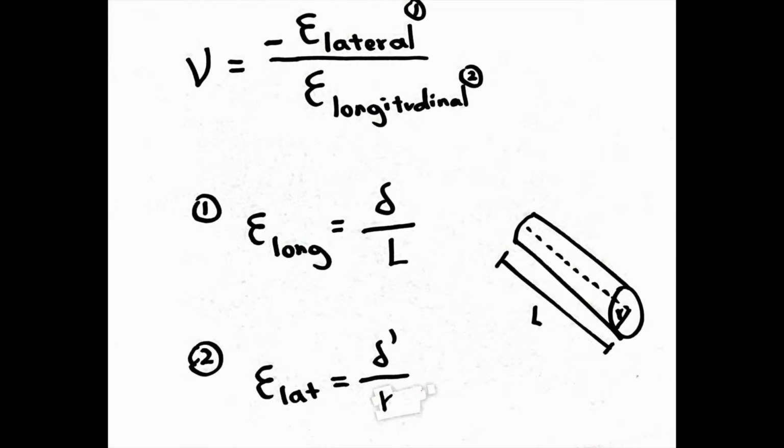So how do we determine the changes in material with Poisson's ratio? Poisson's ratio is defined as negative lateral strain over positive longitudinal strain, and each part can be further broken down with the strain deflection formula into strain equals deflection over length or deflection over radius, depending on the axis of interest, shown on this slide. Now let's look at some real-life demo of the Poisson's ratio.